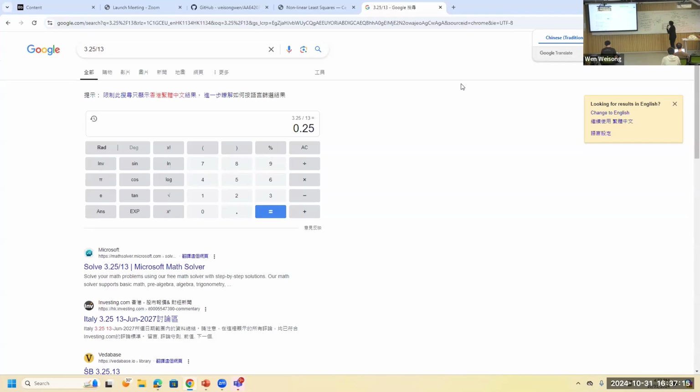For this equation you can move the range rs to the other side. You want to minimize this equation to calculate x, y, and z. It's just the same. If you get the range measurements from multiple satellites, we do a similar iteration process.